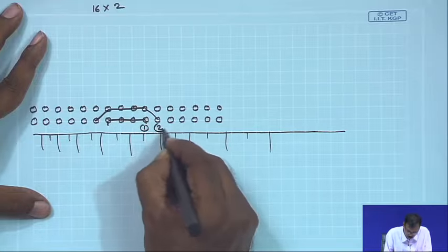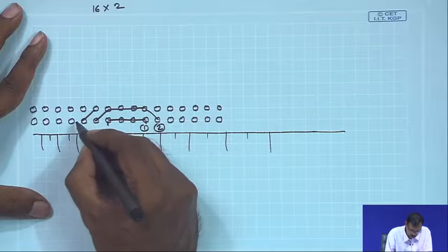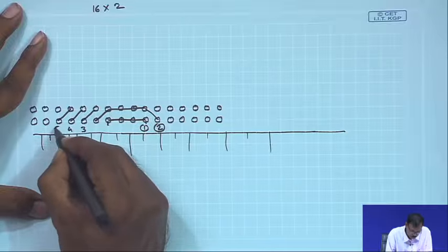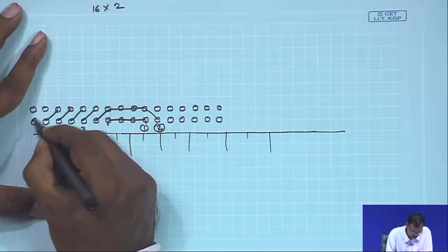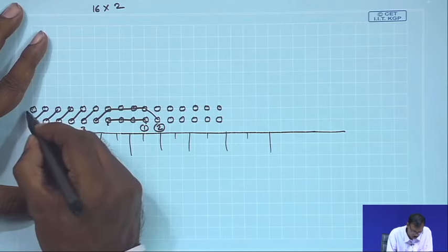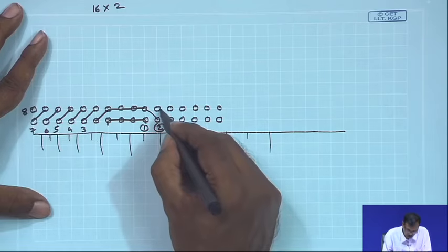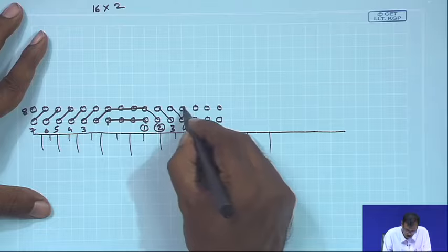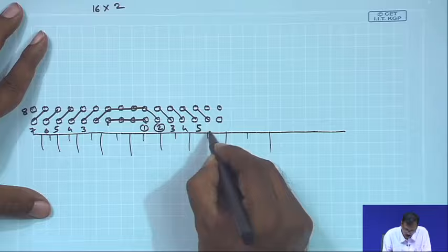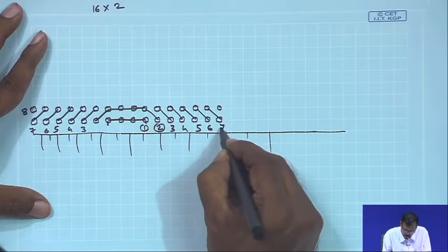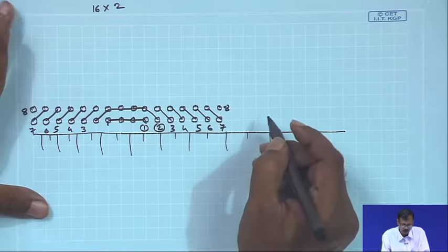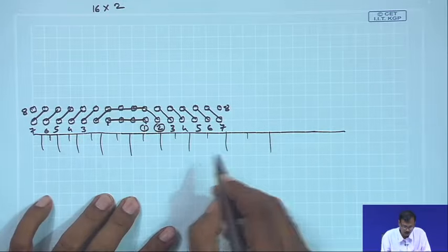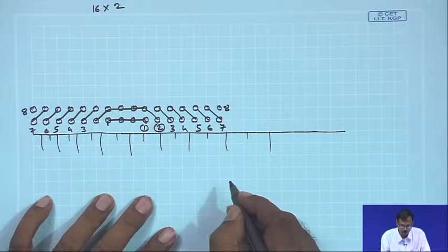So, this will be the delay number 2, then all these holes will be delay number 3, 4, 5, 6, 7 and this one will be of 8. So, similarly, this one is of 3, 4, 5, 6, 7 and this may be of 8. So, this will be the delay sequence for all these holes to achieve this extended V cut pattern.